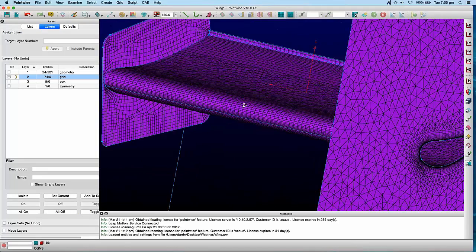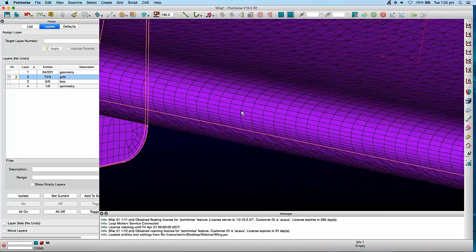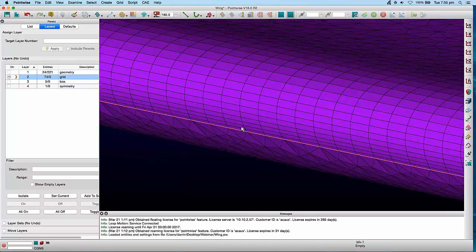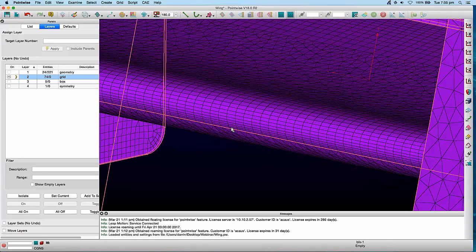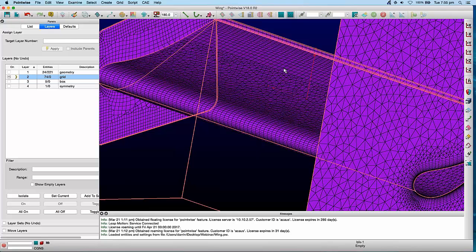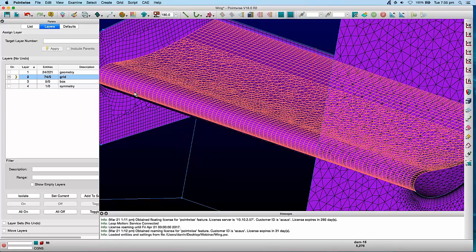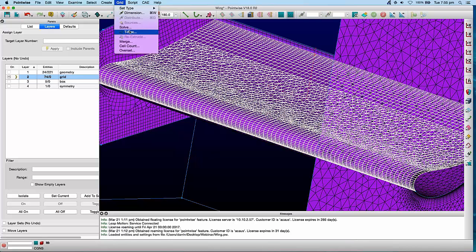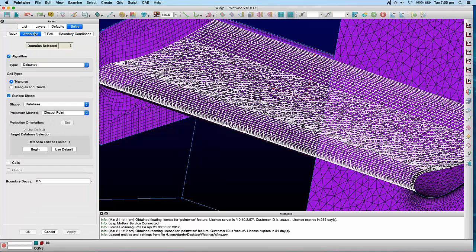You'll see that Pointwise has actually extruded anisotropic triangles, but I told it that it can combine those into quadrilaterals, so it notices it can combine into beautiful quadrilaterals there that come off. As it goes around we get the quadrilaterals at the back, but we still end up with the tris in the middle, and that tells me I've done something wrong because I know I can get quads in there. The reason is that I've set the type to Delaunay and it's set to triangle.